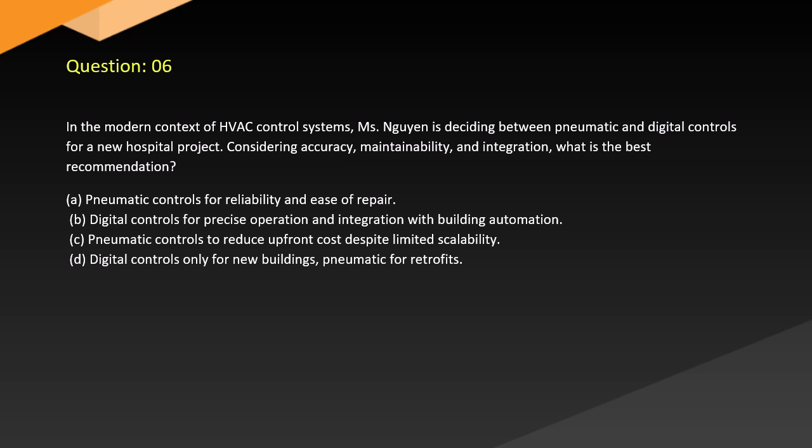A. Pneumatic controls for reliability and ease of repair. B. Digital controls for precise operation and integration with building automation. C. Pneumatic controls to reduce upfront costs despite limited scalability. D. Digital controls only for new buildings, pneumatic for retrofits.